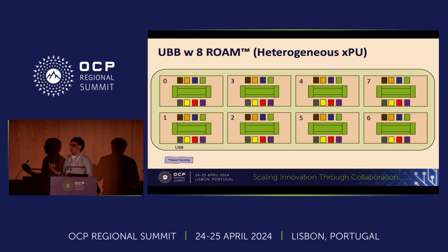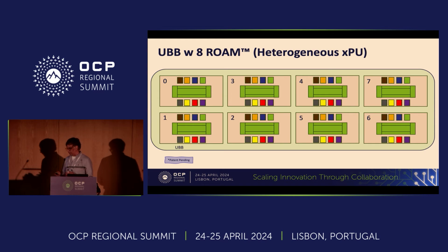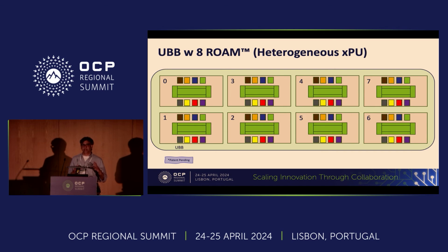Or you could take it to the other extreme, which is you could have heterogeneous chiplets. Heterogeneous has many definitions, different technology nodes or different types of accelerators. Could be inference, could be video transcoding, could be CPU, whatever the case may be, and you can mix and match. But it all goes on the same OAM because the footprints are predefined.